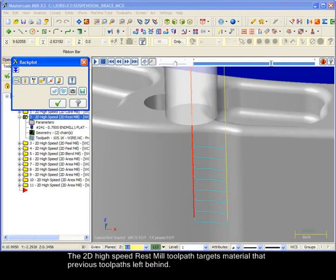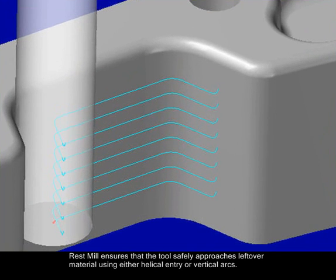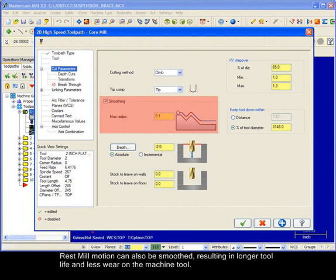The 2D high-speed rest mill toolpath targets material that previous toolpaths left behind. Rest mill ensures that the tool safely approaches leftover material using either helical entry or vertical arcs. Rest mill motion can be smooth, resulting in longer tool life and less wear on the machine tool.